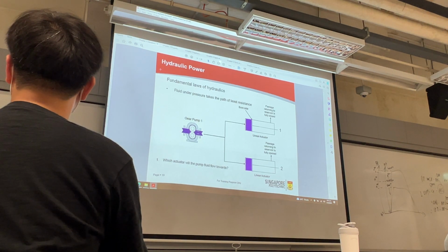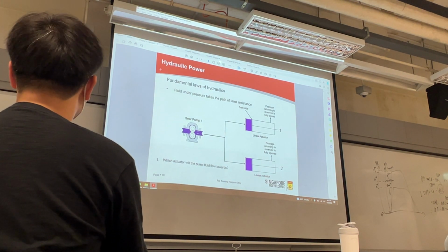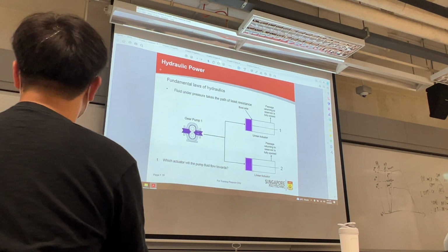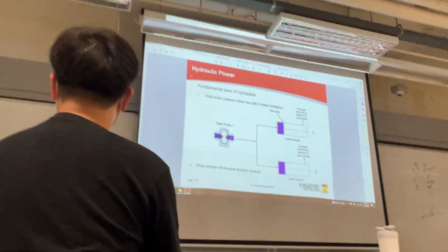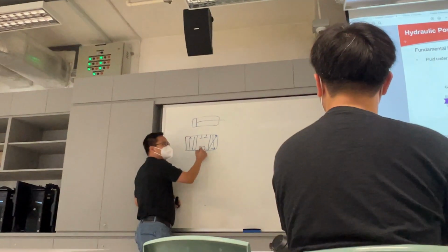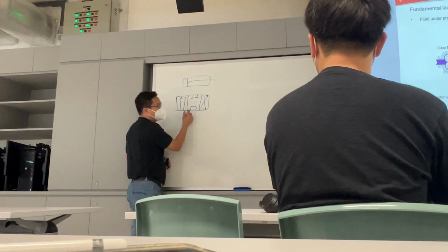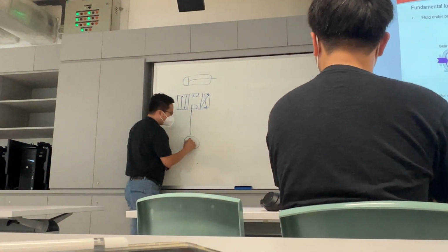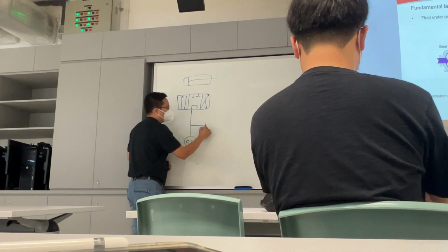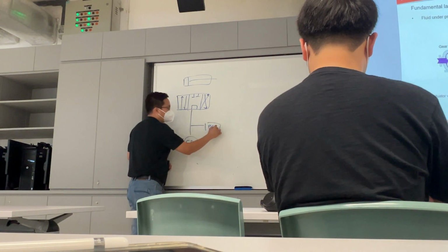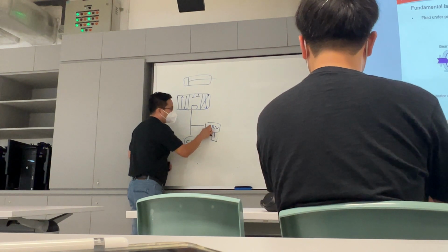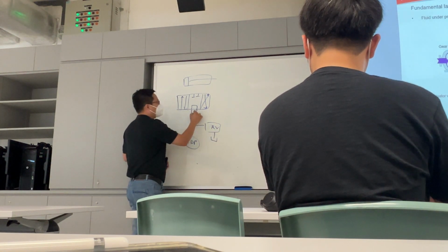Now, in the experiment where Mr. Roger has to demonstrate to you, we have what we call the open center selector valve. How do we know? Because this is going to be a C shape. Now, in your pump, a constant displacement pump, in that experiment, we have a pressure relief valve, and then the relief valve goes back to the reservoir.